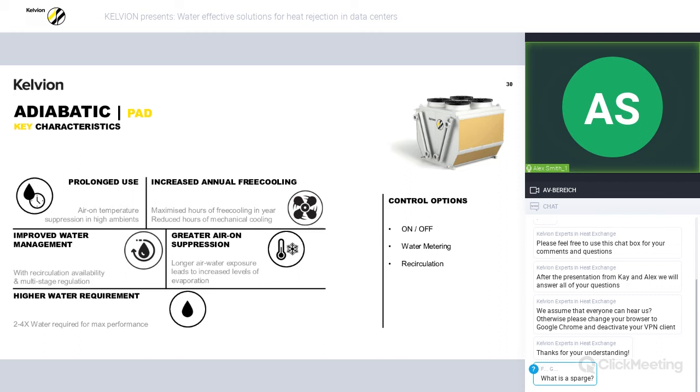This comes at a cost, as pad systems are often far more expensive than spray systems. Pad systems typically require large volumes of water to be poured over them to ensure effective operation and to minimize dry patches, which can lead to significant waste if the wastewater isn't managed.